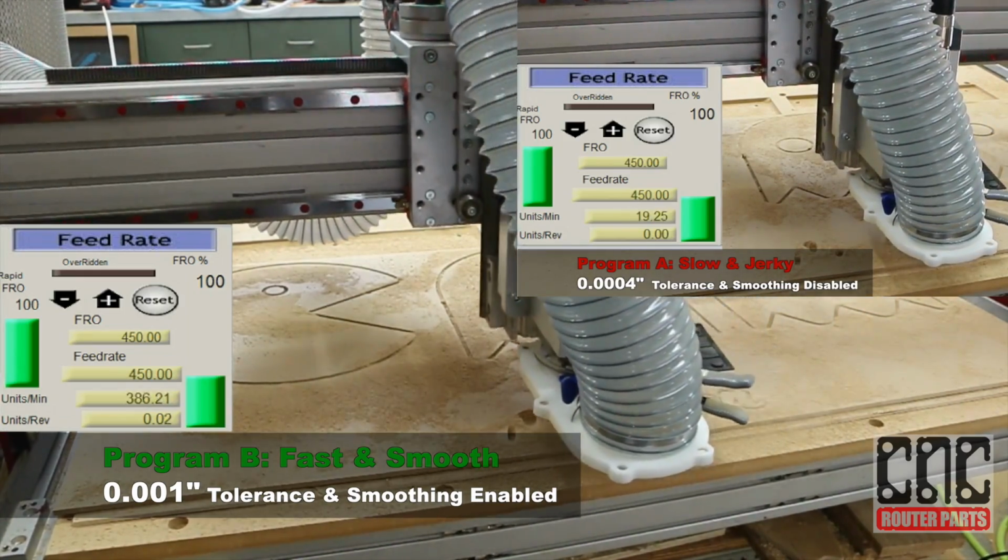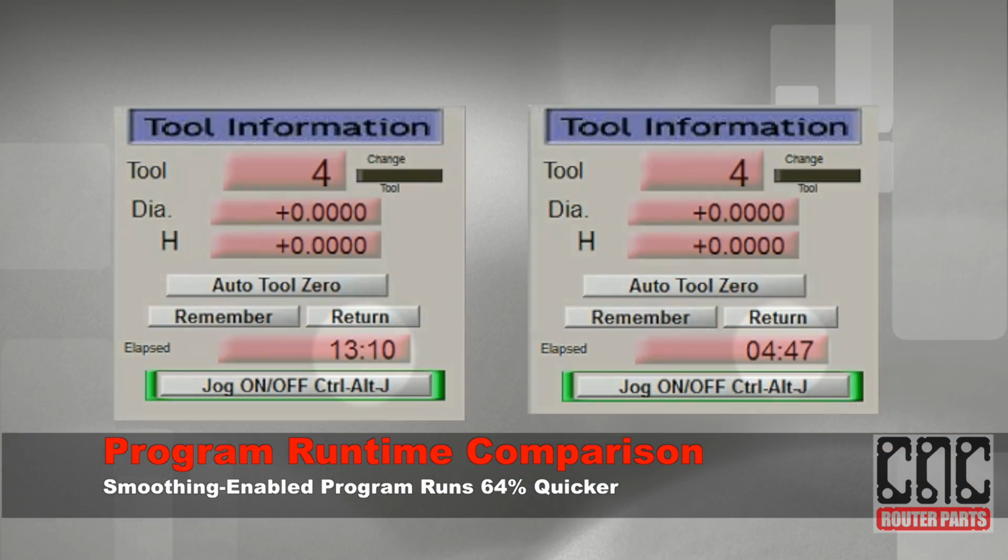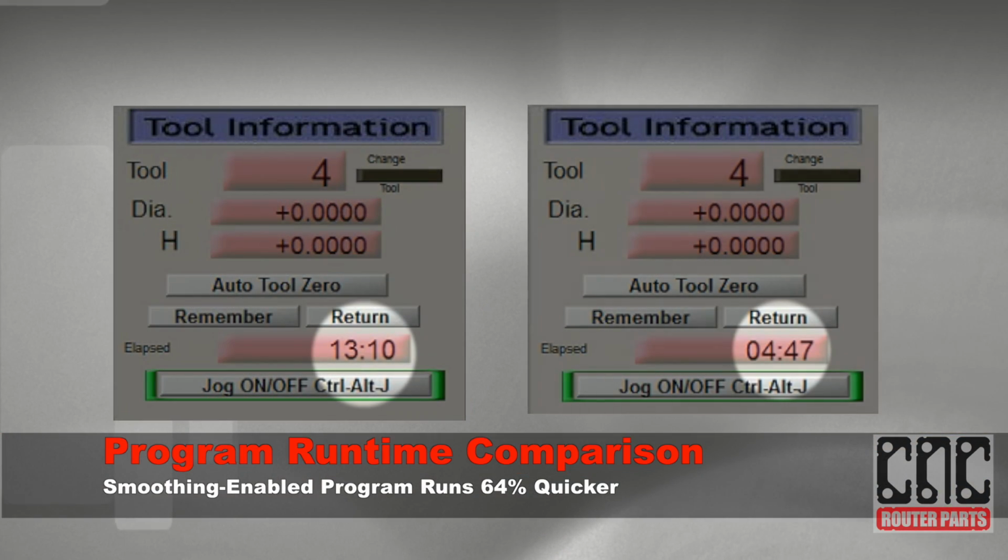Here's a screen grab of the operator console after each program executed. You can see that program B on the right was significantly faster, 64% in fact, and resulted in a better part finish. This is obviously a simple example project. However, in cases such as this where there are few mechanical clearance or tolerance requirements, we could have tuned it quite a bit further with a higher IPM and more aggressive smoothing.